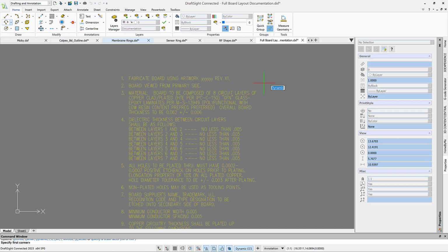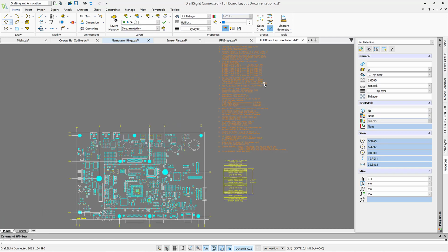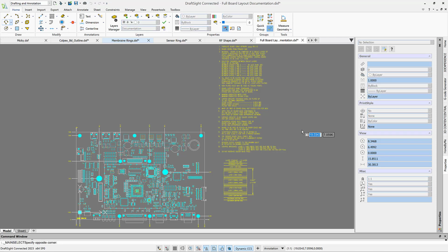So basically, what we can do is include all of this information inside the mechanical software so we don't bog down and use a very expensive PC board layout software to do this task of adding notes, cross sections, and title blocks. You can use that PC board layout software for doing complex auto routing, calculating the delays, and interfacing with the simulation software. So you leave the simple stuff for documenting this layout to mechanical software like DraftSight, which is a great help.